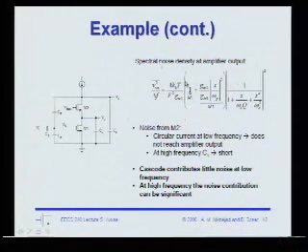If you look at the total noise that you get from the device, it has a contribution that just looks like the noise of M1, right? This expression, forget the F, looks like just the noise of M1. And then you have this gain factor, which is the noise of M2. And you can see that it's also proportional to the ratio of gm2 to gm1.